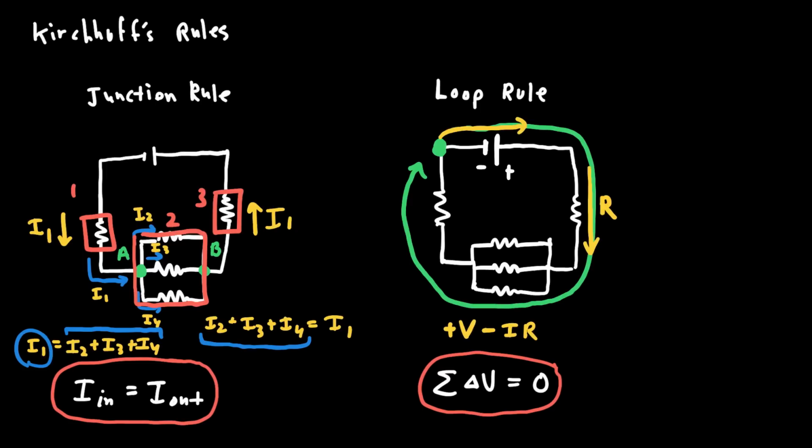The next thing that I'd like to point out is, let's say that one of these resistors right here has a voltage of 1 volt. How could we proceed? Do I have to add 3 more terms to this equation for each of those resistors, or is there a more clever way of thinking about this? Well, first off, I know that if the voltage drop across this resistor is 1 volt, then the voltage across those 2 resistors is 1 volt, and the voltage across this resistor is also 1 volt, which means the potential difference between these 2 equivalent points in the circuit is 1 volt.